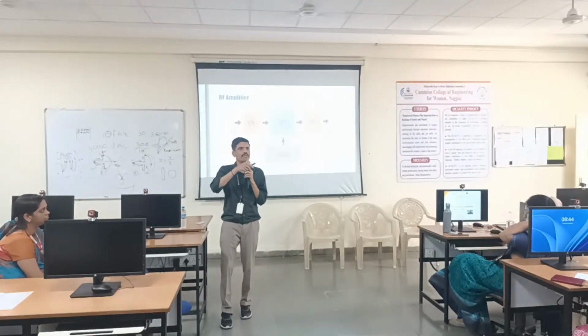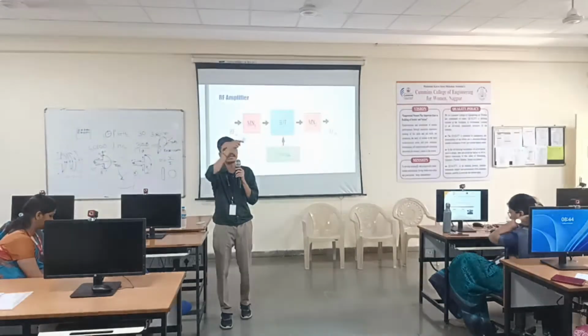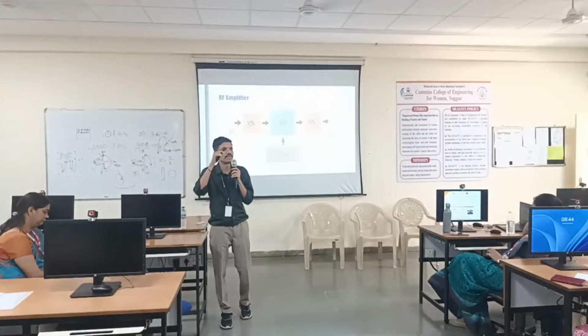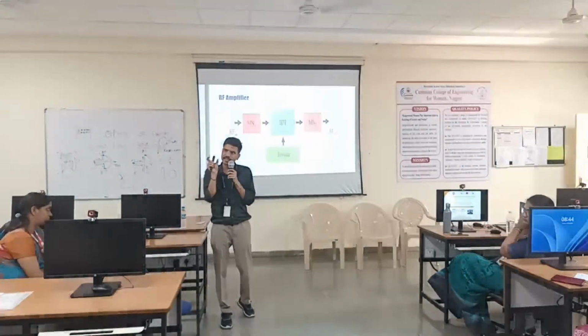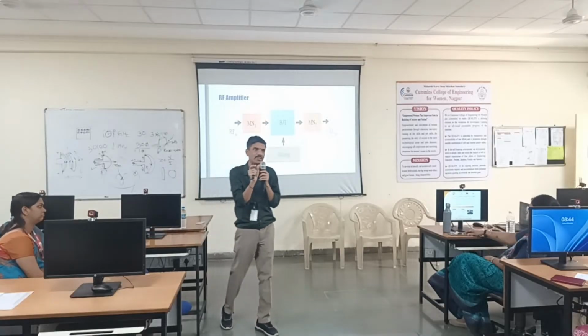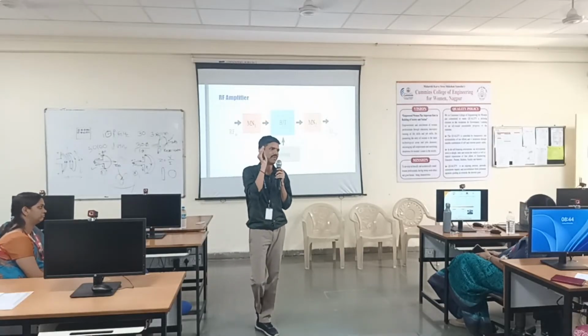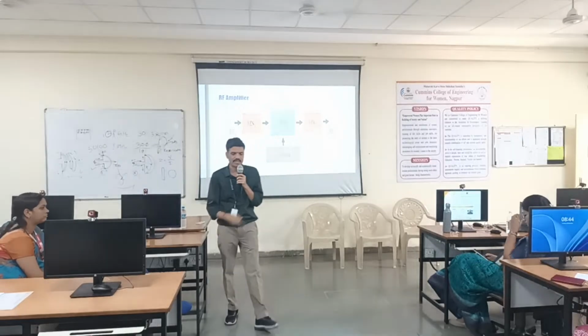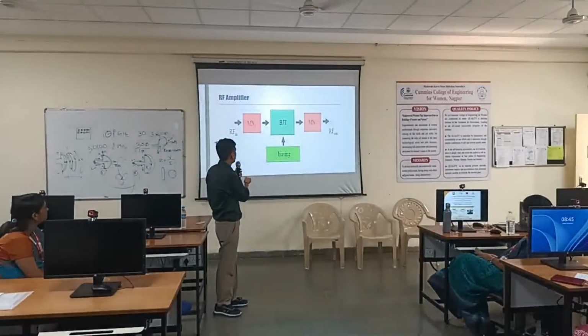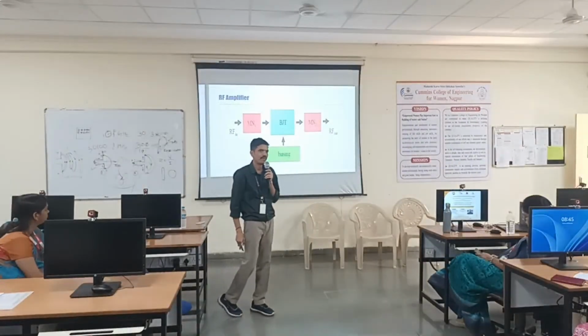There is a graph. If you search on Google, you can see the power handling is maximum and losses will be minimum. So those numbers are 75 and 32. If you take the mean of that, you have optimum power handling and optimum power loss, or you can say close to minimum power loss. So that number is 50. Okay. So the first job, matching network 1 will match 50 ohms with whatever impedance we have at the input of this transistor. What will be that number?